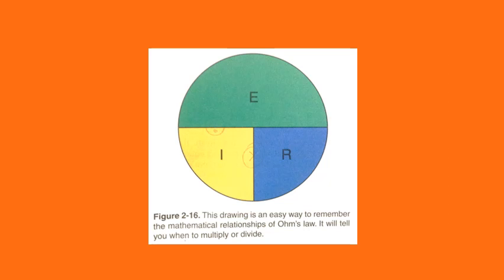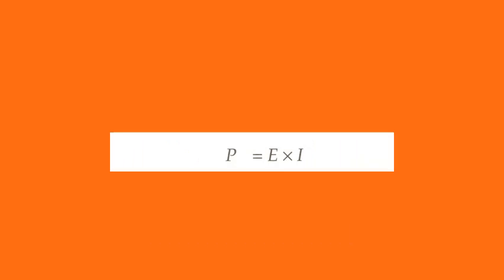Power and work. Electric power is a combination of current and voltage. It is actually current times voltage. Power expresses the rate at which electricity is being consumed regardless of the voltage or current. For example, a 120 volt air conditioner drawing 10 amps of current is using the same amount of power as a 240 volt air conditioner that is only drawing 5 amps of current. The power in both cases is 1200 watts. Power indicates how fast a certain amount of work can be done.